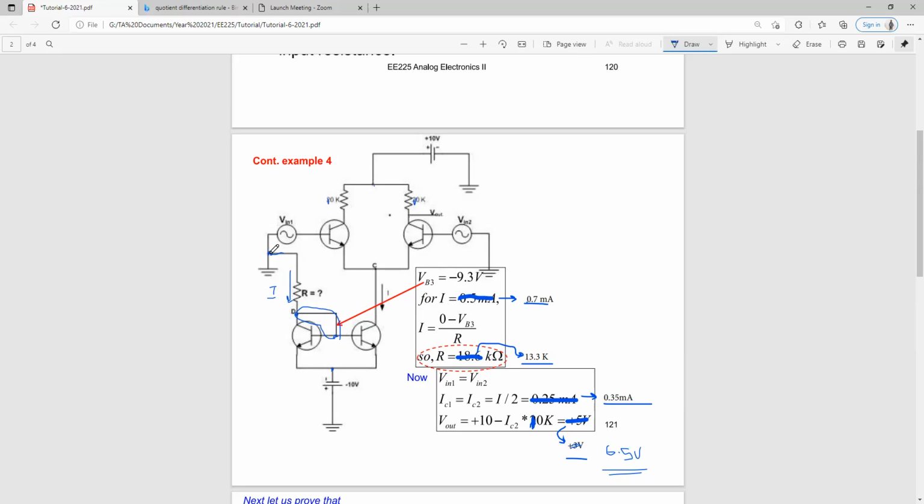The current basically flows from high voltage to low voltage. So if we write the branch equation or the nodal equation for this particular branch, the current in this branch is equal to the high voltage, since the current is flowing in this branch and this terminal will have the high voltage, so it is zero minus whatever voltage we had at this particular node, divided by resistance.